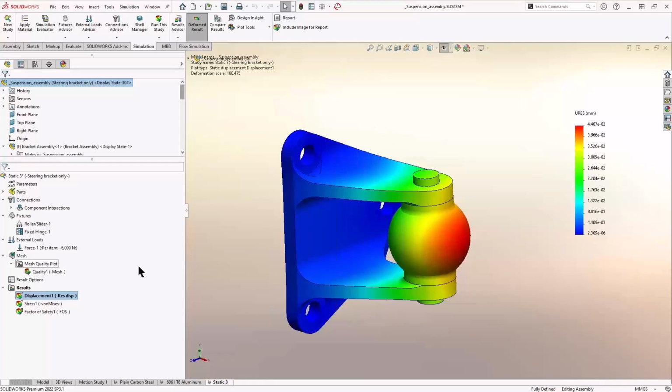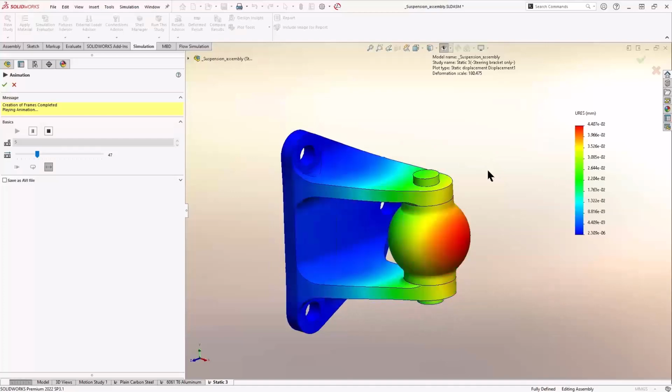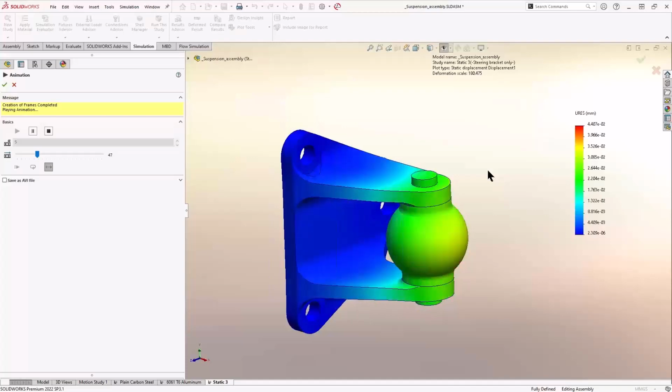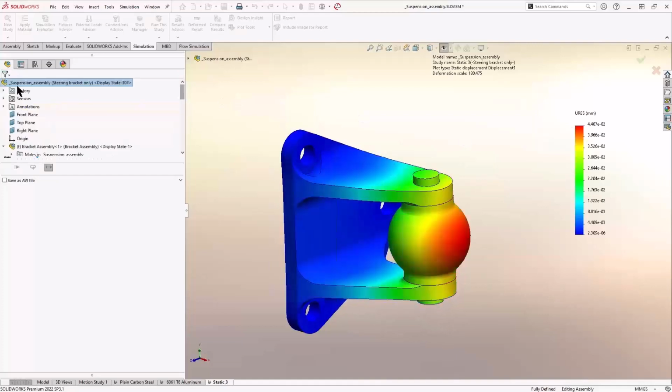And what I'm really looking at here is if I right-click my displacement plot and animate it, does the direction of the displacements and the place where I see the maximum, most red, does that make sense? In this case, yeah, red's not bad. It's a very small number, but that's where the most is. That's where I'd expect it to be. Those are the directions, so I probably set things up correctly.